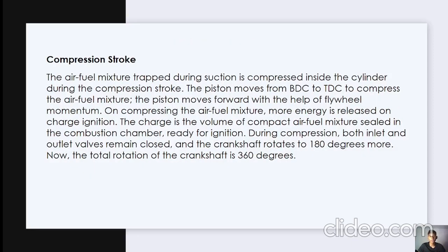During the compression stroke, the piston moves from bottom dead center to top dead center to compress the air-fuel mixture. The piston moves forward with the help of flywheel momentum, compressing the air-fuel mixture. More energy is released on charge ignition. The charge is the volume of compact air-fuel mixture sealed in the combustion chamber, ready for ignition. During compression, both the inlet and outlet valve remain closed, and the crankshaft rotates 180 degrees more. The total rotation of crankshaft is 360 degrees.